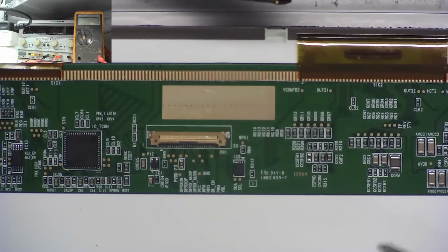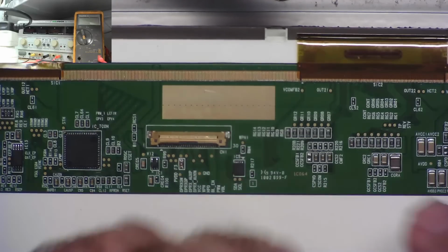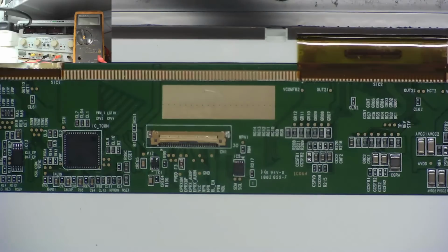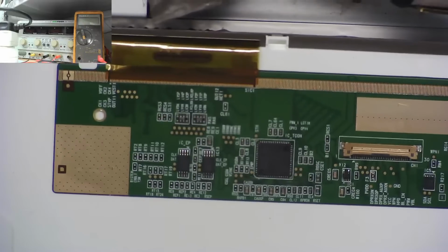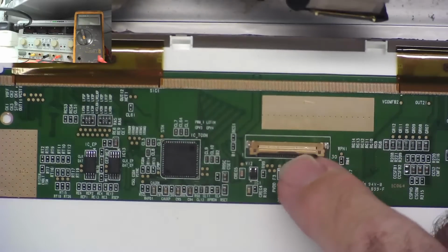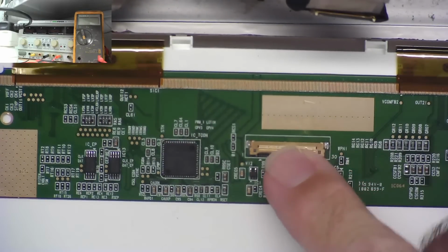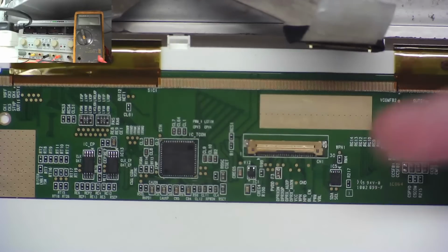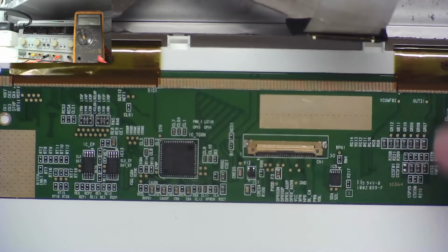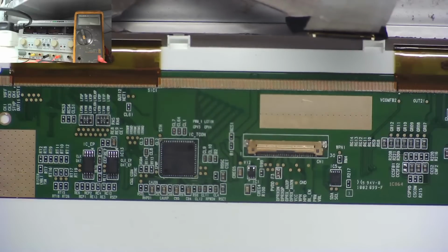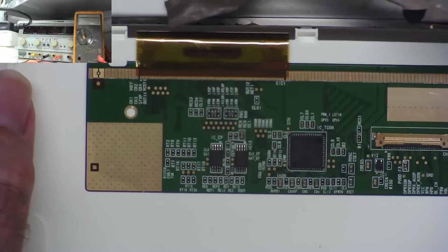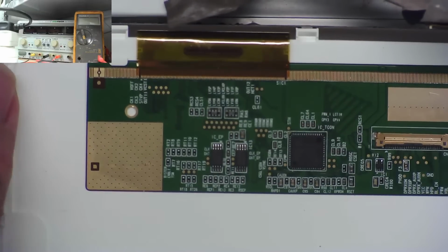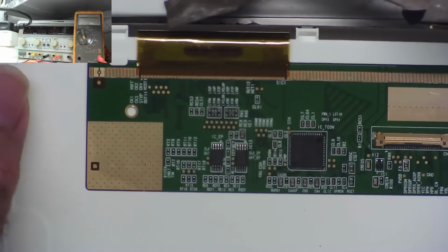So behind the panel will be LED lighting, not LCD, LED lighting. I'll get the center set in a minute. And this is like a controller board. So coming in is your power. There's only one cable coming from the laptop, so this is the power for the backlight, controls the brightness of it, and effectively sends the data into here. This is what would be called a TCON, timing controller board, basically on a TV.